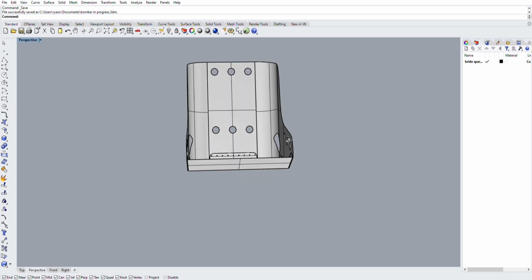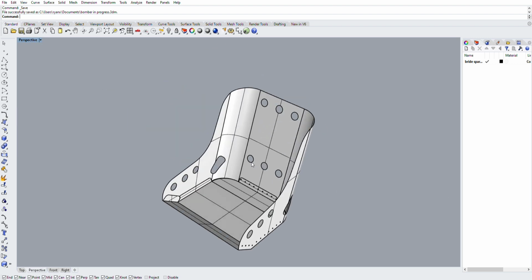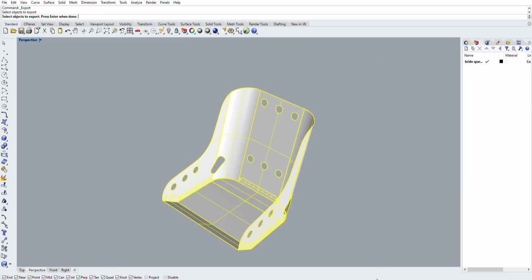You can see it there. And the outer skin, the back and the sides, the material will be on the outside of that, so it doesn't affect the fitment to the flange at all. But this means that even if I messed up bending the flanges a little bit, I've got a little bit of wiggle room so that I can drill my holes. We'll drill one at a time, put a cleco in them, and eventually hard rivets, and we're good to go.